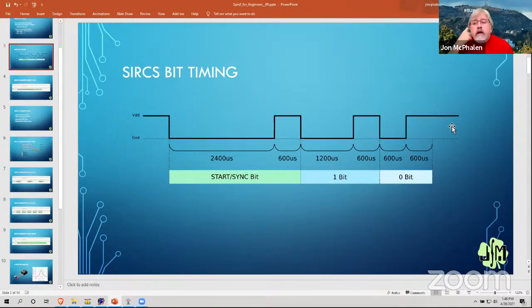But this was where, for example, with the basic stamp, we didn't have this opportunity, because with the basic stamp, we just had pulse in. And what we would do is pulse in and then grab 13 pulses, because we were counting on using a 12-bit remote. And so then we could look at the pulses. The first one was going to be the start pulse, so we could just get rid of that.